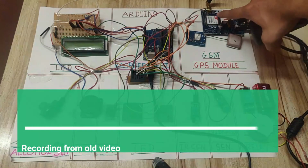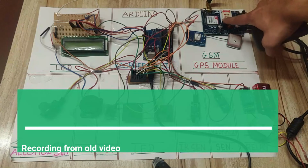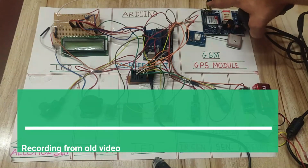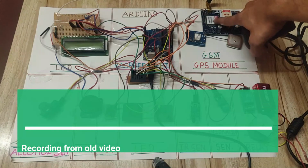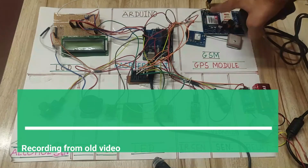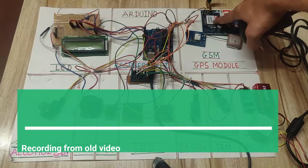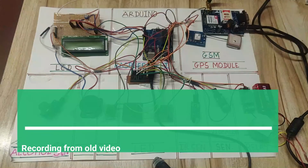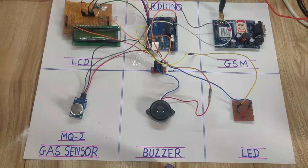You should not connect the VCC pin of this SIM 900A to the Arduino pin. Only connect the ground pin of SIM 900A to the Arduino pin, and the RX pin of SIM 900A to the Arduino TX pin. That is the only part. So in this way we have completed the circuit connection of our project.